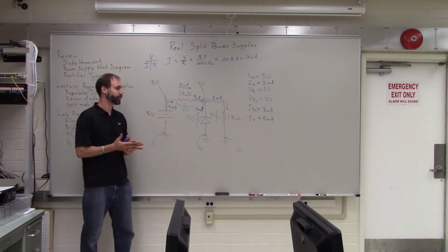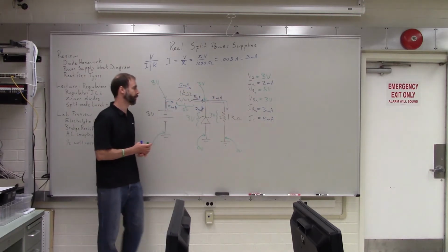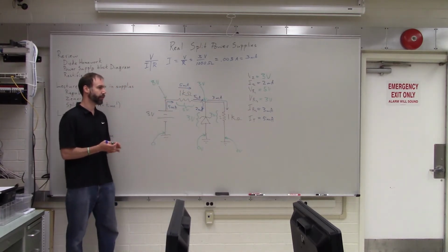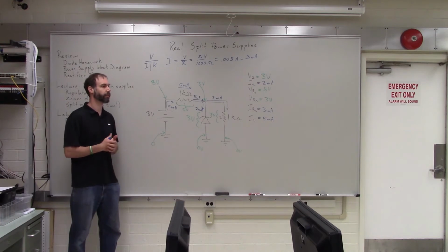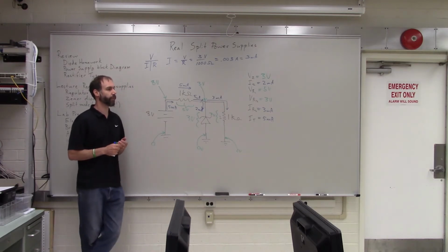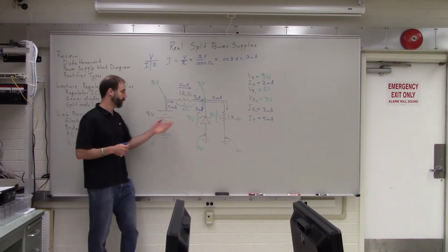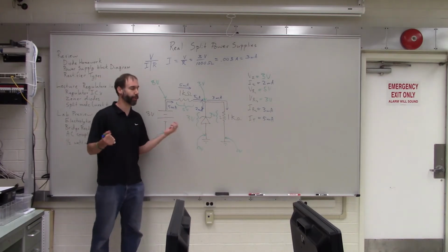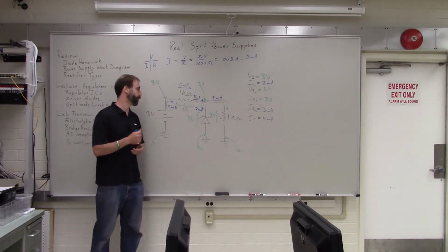So we are not calculating resistance of the diode at all? Right. There's no calculation for a resistance for the diode. Because sometimes, if you look at other examples, you need a resistance to find current or whatever, and you may use it for the diode to find other components in the circuit, but you cannot assign any resistance to diodes. Right. You can't just say this diode has a 100 ohm resistance. It doesn't work that way.